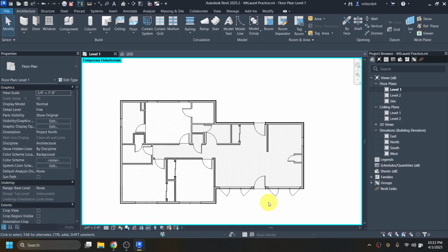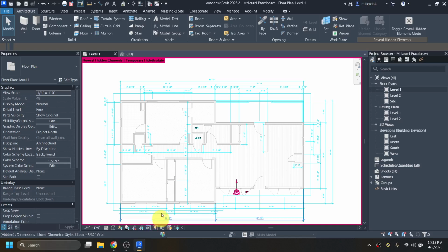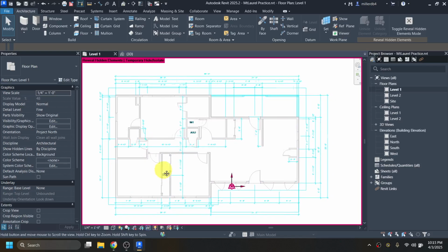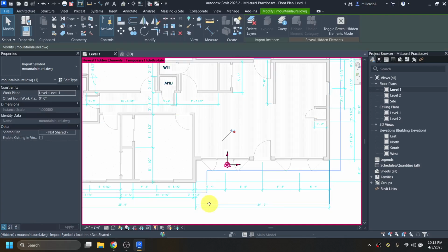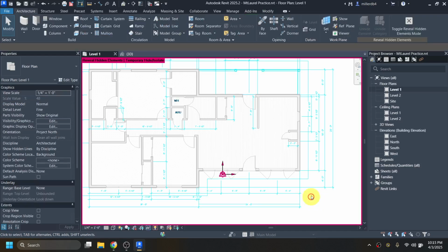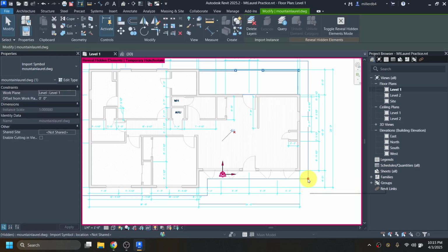Next, let's add a foundation to her. Actually, let's add our decks in next, and then we can delete our AutoCAD drawing. So I'm going to bring my AutoCAD drawing back real quick by clicking on my little light bulb here, selecting the AutoCAD drawing, which is kind of hard to get, but it was that line there, or this big thing around it.